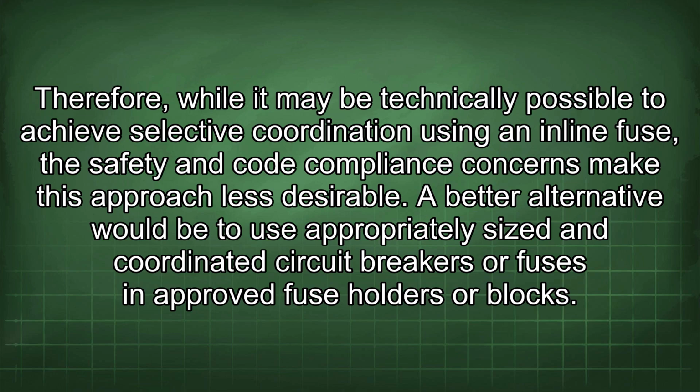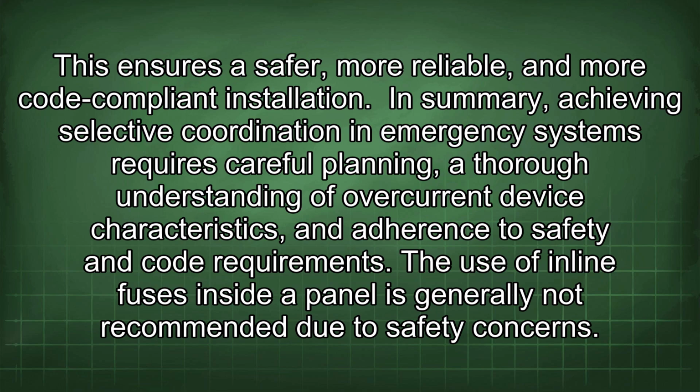A better alternative would be to use appropriately sized and coordinated circuit breakers or fuses in approved fuse holders or blocks. This ensures a safer, more reliable, and more code-compliant installation.